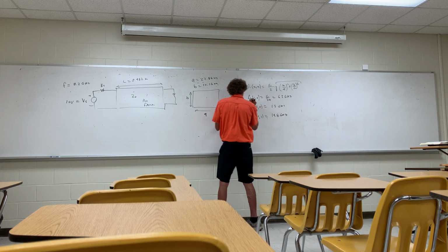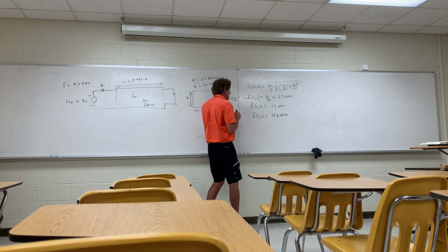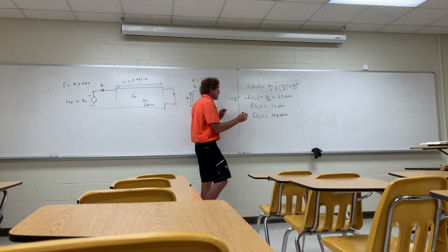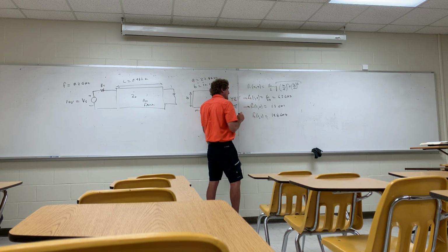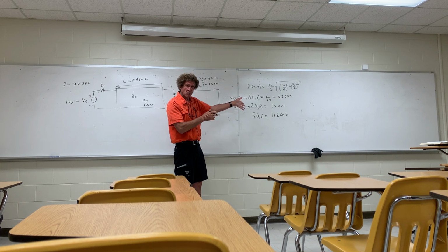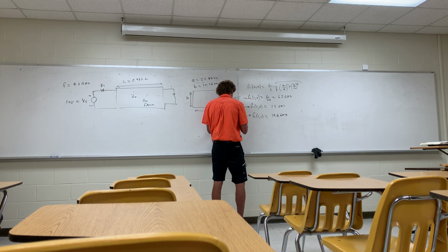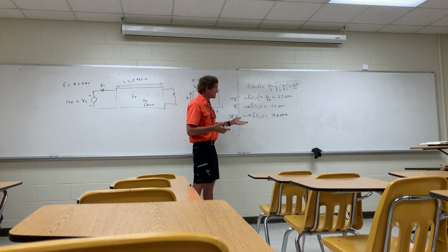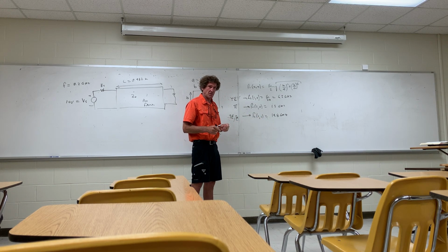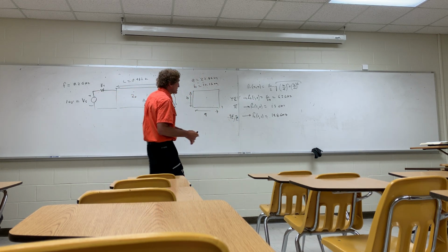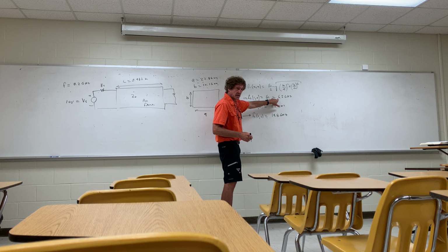Now, I want to make note of this. This can only be a TE mode. The 1,0 is only TE, no TM. Follow me on that, class? Everybody? Now, this mode, the 2,0, is only TE. So you should put TE10. Follow me? Now this could be TE or TM. Both modes will be excited if the frequency of operation is greater than 14.8 gigahertz. But these can only be TE. Now we look at the operating frequency, it's 8 gigahertz. This mode will propagate, it'll be developed. This will not, it's too high frequency. So there's only one mode of operation, as it should be. Everybody got that? All right.